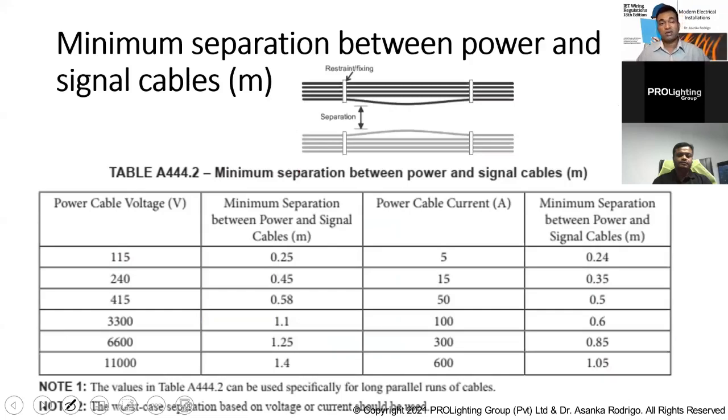And the other thing is, nowadays, as I said, we are not only working with power frequency, we are now working with many high frequency components as well. In our system, most of our systems are now distorted because of harmonics, because of other types of interference, high frequency, switching, those types of things. Because of that, the standard added a new requirement: when you are running these cables, you need to maintain minimum separation.